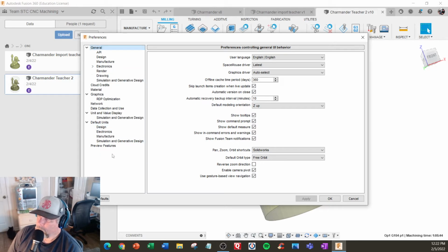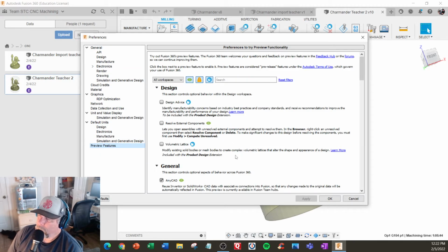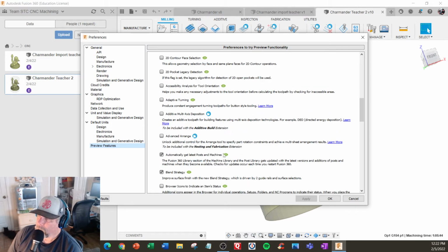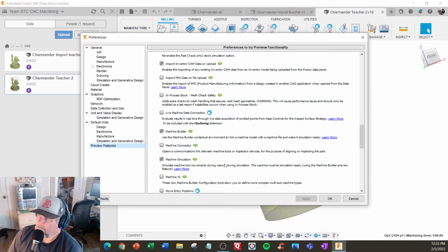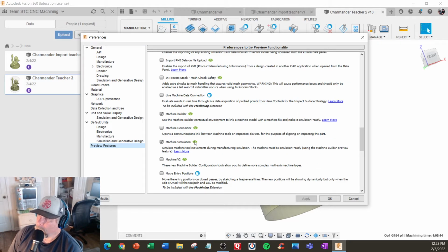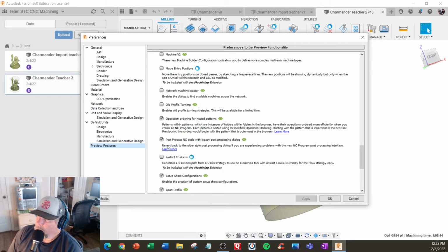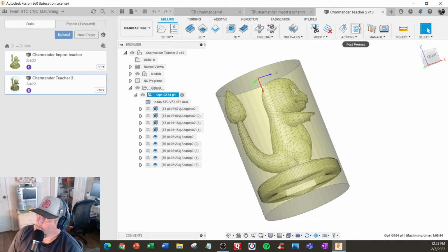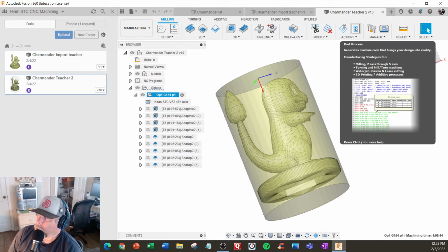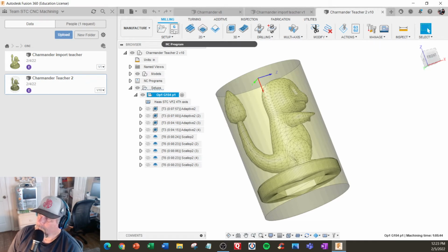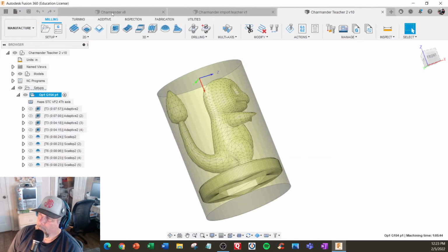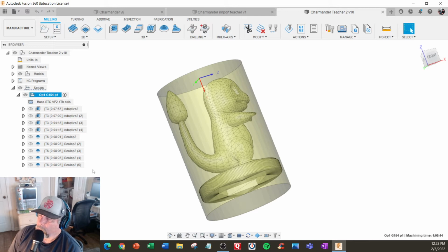So, as far as basic setups, under preview features, now in education, we actually have more access to the manufacturing extensions, like the multi-axis stuff and our machine simulation. But we've actually turned on post-process NC code with legacy post. It's just our preference in the school to use the G1 tab to produce the code versus the NC program area, even though we have it here. So we wanted to learn the benefits of either one.